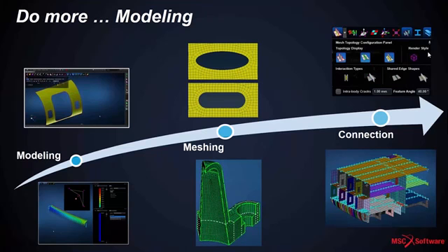Plus, when the holes are close to each other, or when the holes are close to the boundary, we are giving treatment to the meshing so that it takes care of the quality of the mesh and creates good quality elements around those holes and the washers and also close to the boundaries. Likewise, there are enhancements in the connections, in particular the tie connections. Since Apex is targeted for large fabricated structure simulation, we are introducing enhancements in the usability and what is called the topology visualizations.